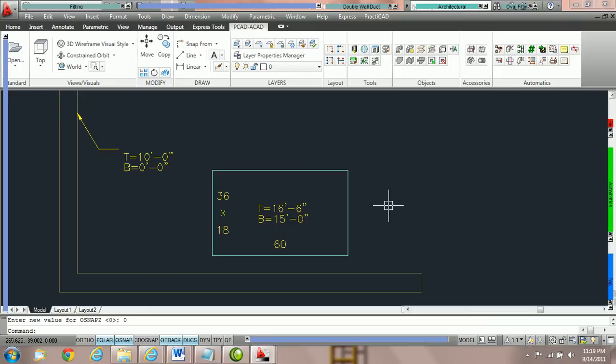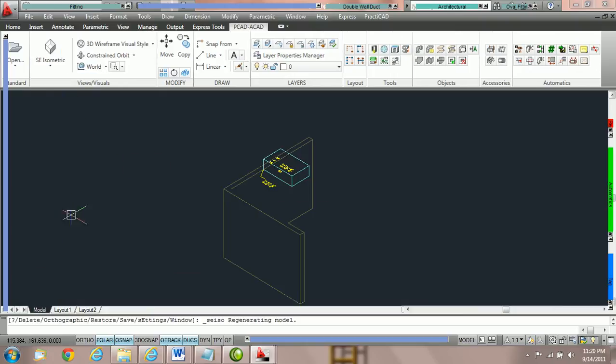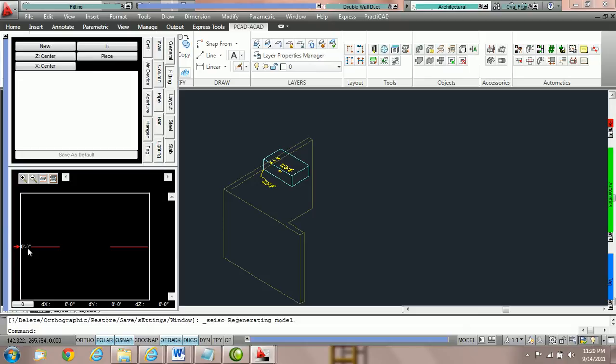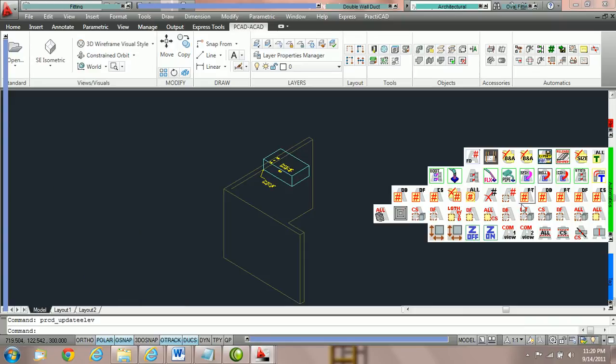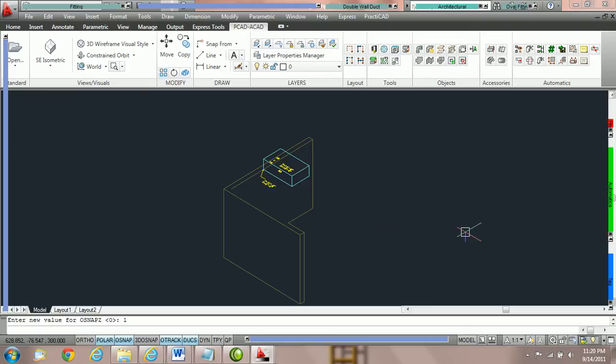Also some quick methods we've created to make it easy to work with this feature. You cannot leave Replace Z on all the time. To demonstrate an area where you might get into trouble if you do, we're going to rotate this drawing into the southeast isometric. Now just imagine we had placed something on the drawing at 25 foot, and that was our current elevation. And I'm going to basically keep the Replace Z on.